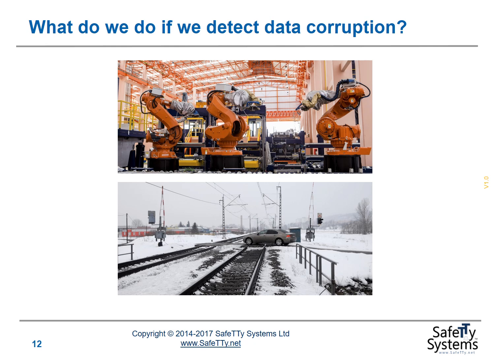In the second situation below here, if we detect data corruption in this situation, simply shutting the vehicle down would clearly not necessarily be a sensible option. If your car stops in the middle of a level crossing and you're hit by a train, that's not an ideal outcome. So typically in this kind of scenario, if we detect a problem in the control system for the vehicle, we would want to enable not an immediate shutdown, but some kind of recovery option, including some kind of